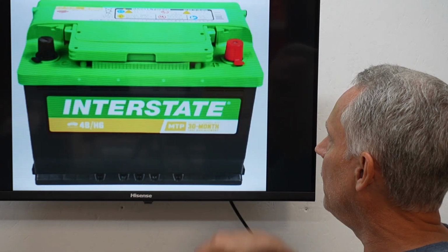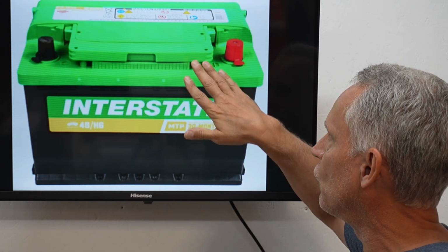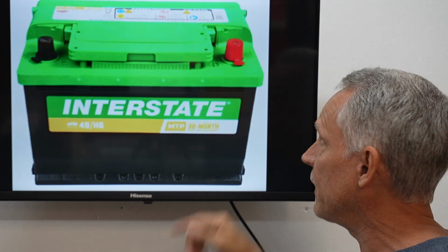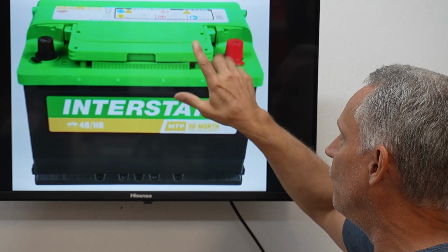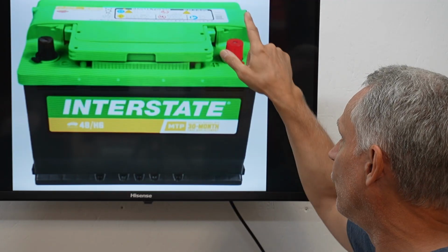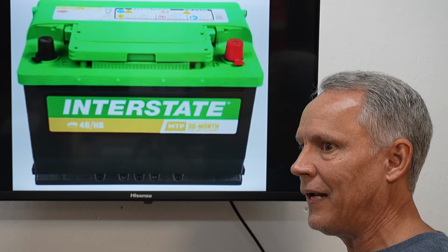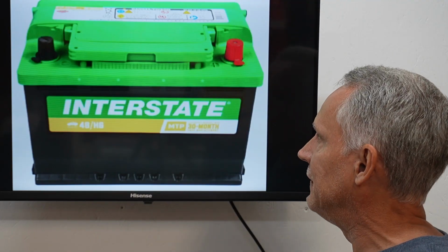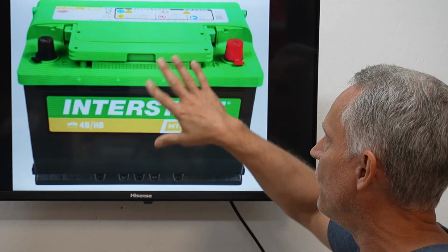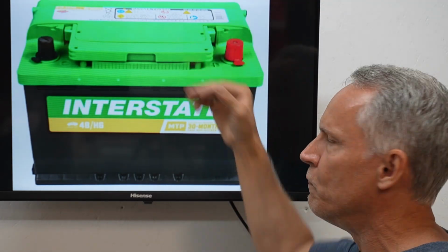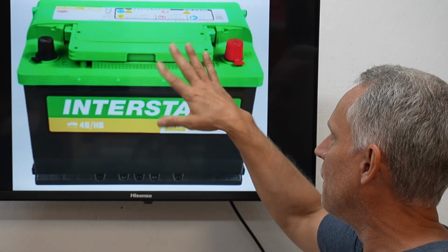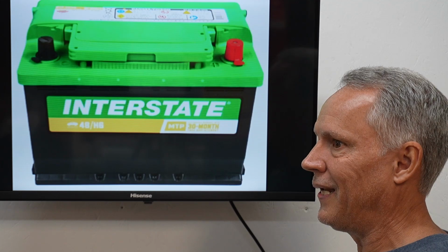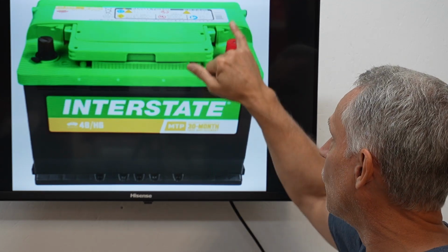One thing of note, if you replace a battery like this in your car and it has a side vent, you'll find that the vent itself has a tube attached to it. That tube is designed to vent outside the vehicle. If you follow that tube, you'll find it goes outside, literally under the vehicle, through the inner fender. If this type of battery was mounted in the trunk, you don't want the fumes getting inside the passenger compartment. If it was mounted inside the car somewhere, like under a seat, obviously you don't want the fumes getting inside the passenger compartment. So they'll vent it outward.